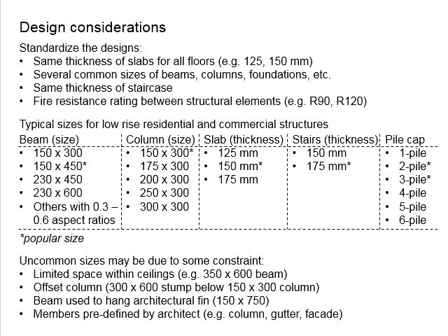There will also be items meant for supporting the architectural things, especially those not within the floor plan, which have a certain distance from the top surface of the beam or from the soffit of the beam. In this case, you might need to enlarge your beam section, either to increase the height or to lower the soffit, in order to hang these architectural things.